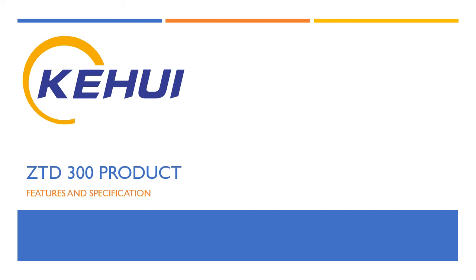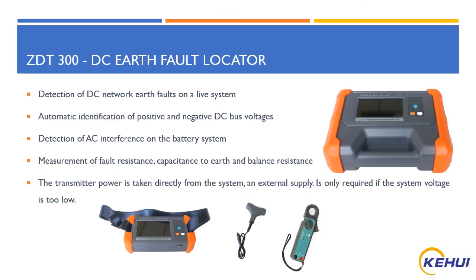So coming to the product features and specifics, you have a transmitter unit, a receiver unit, and a sensor. You get two different sensors with this particular supply. This equipment helps you to identify the DC faults in the live or online system. It also gives you clear automatic identification of positive or negative bus voltage drops. It gives the information if there is any AC interference in the battery system. It measures your fault resistance, the fault capacitance, and also gives you the information of the balancing resistance.